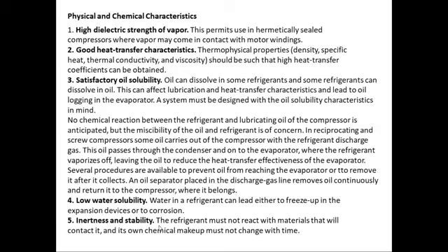Inertness and stability. The refrigerant must not react with the materials that will contact it, and its own chemical makeup must not change with time. So it should be stable. Its chemical composition should not change as it goes through the phase change process, and it should be inert with the material with which it is coming into contact. That is copper in the evaporator, or aluminum in the condenser, or any other steel parts or any other plastic that it comes in contact with, it should be inert. It should not react with those materials. So that's what inertness with the materials means.